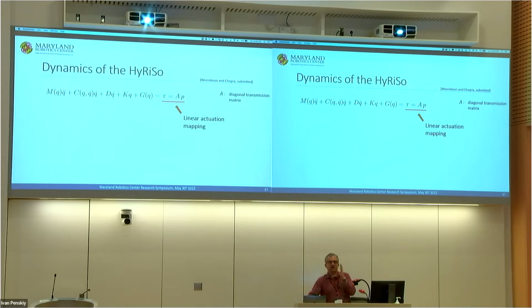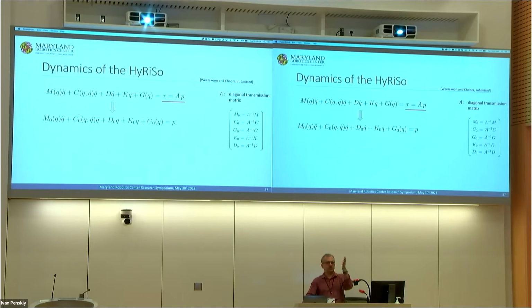We wanted to come up with a framework for controlling these robots. On the right that you see is what we call an actuator mapping. The idea is that I do not know what the actuator mapping is. I have these pneumatics working, I have the drives working. So can I come up with a way of computing control of these robots? In this specific case, we just talked about trajectory tracking. Using these kinds of formulations, one of the things we saw was that there is a property that we use for controlling rigid robots, which is called linear parametrization. And that allows us to do a lot of control of these robots when I don't know what the mass is, what the actuator mapping really is. We can get around most of these things just by using either adaptive control or robust control methodologies.